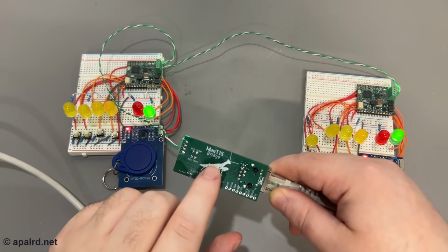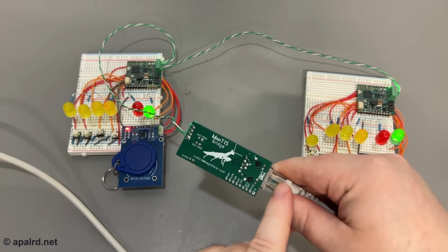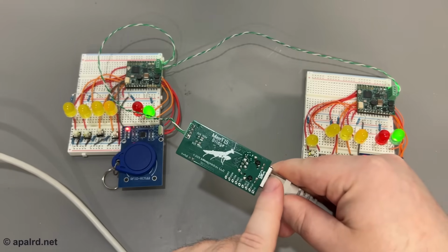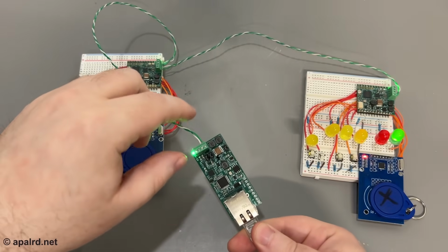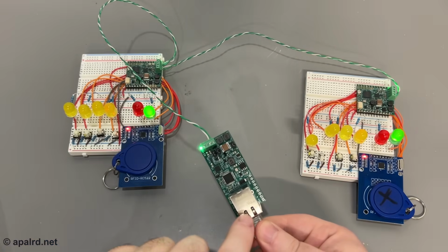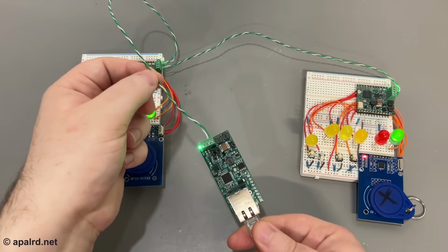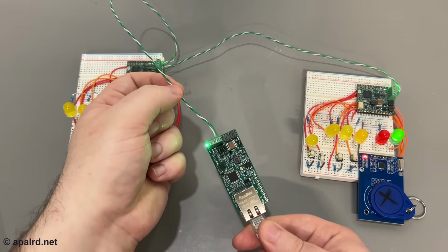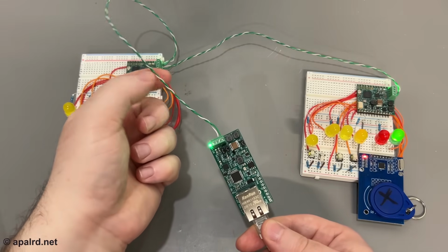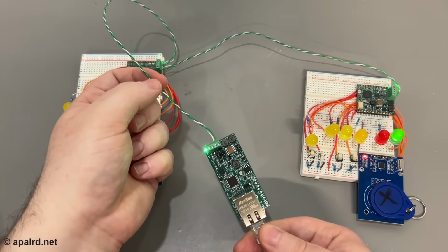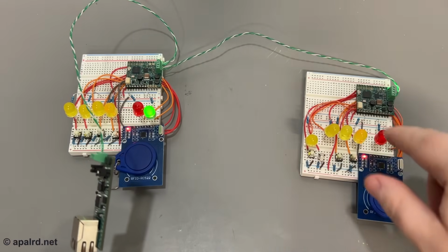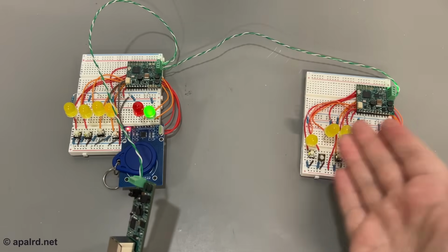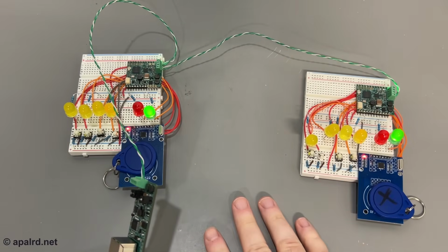The Mantis bridge, MAN-T1S. So this takes a normal 10 megabit Ethernet and it converts it to the shared bus here, T1S. And it also takes PoE power and powers the bus with 48 volts. So this is two twisted pairs here carrying 48 volt power and also 10 megabit Ethernet up to about 30 meters. And so I can just daisy chain them down this. I can have up to 8 devices on one segment, which is pretty cool.